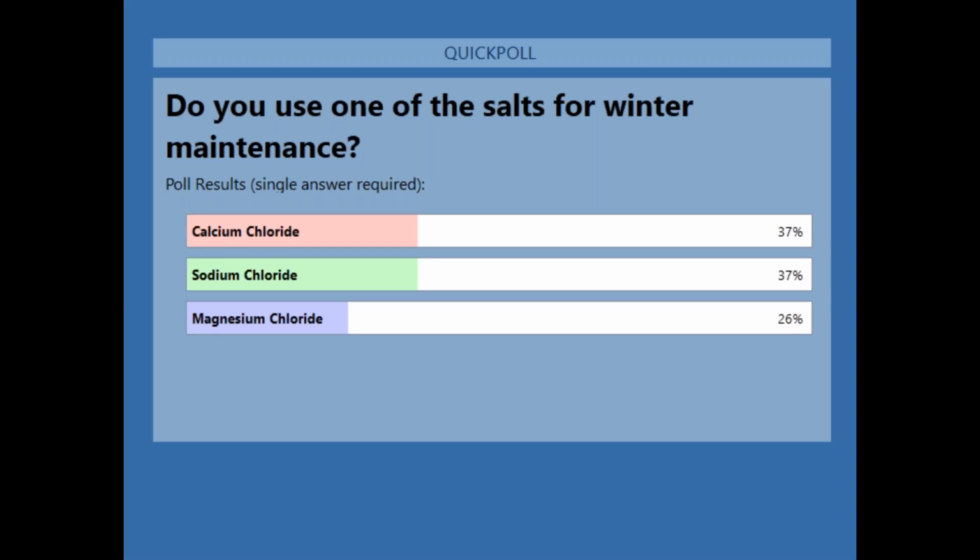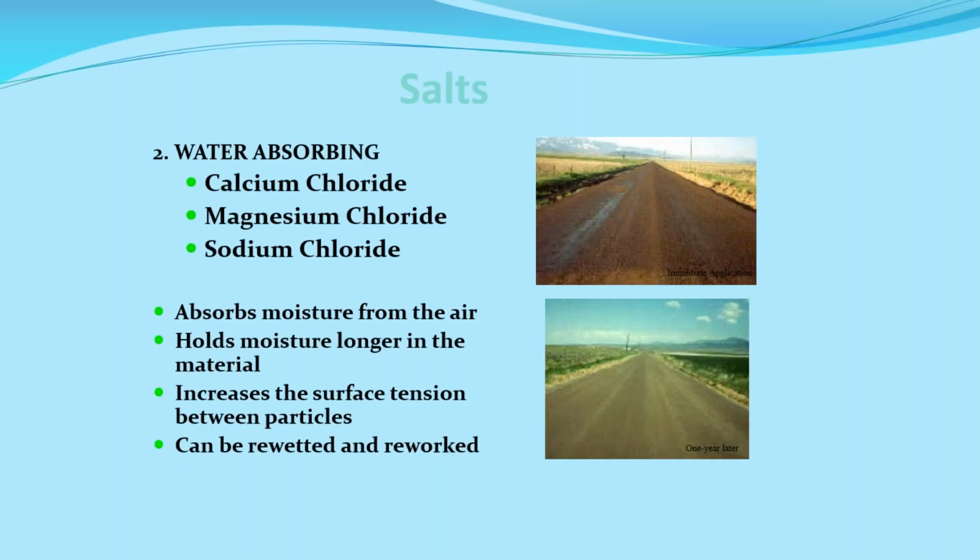And that's actually some of what I talk about in my winter maintenance training, the differences between calcium chloride, magnesium chloride, and sodium chloride. I've dealt with an agency over in South Dakota that uses a combination of calcium chloride with magnesium chloride as a pre-wet. It's very effective in getting rid of the ice, but by the same token, they have a lot of issues because it also damages some of their newer concrete work along their roadway.